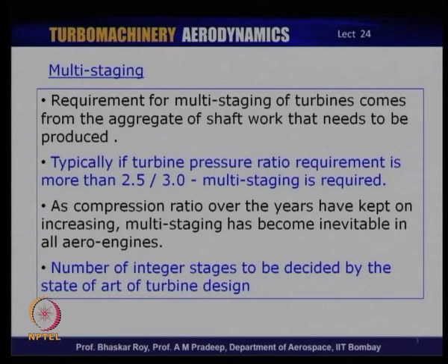On the other hand, the compression ratio of gas turbine engines has kept on increasing over the years, and as a result, to supply that much aggregate power to run a multi-stage compressor, multi-staging of the turbine has also become inevitable, especially in the aero engines, and more so in the land based gas turbine engines, which are anyway much bigger than the aero engines, and they are getting bigger and bigger. In them multi-staging is almost an inevitable result of the present configurations.